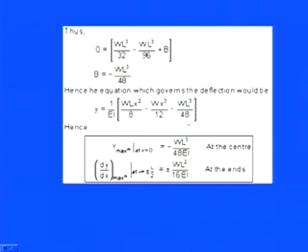Now we have a clear feeling that this deflection due to the point load varies in a cubic way, because the total dimension in every term is cubic. So the variation is in cubic form, and you can put the value of x in terms of L and get the deflection at different points.